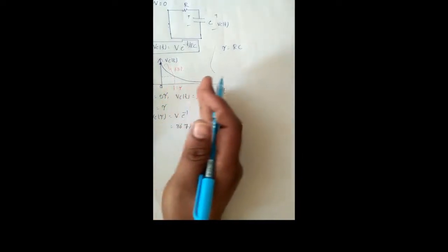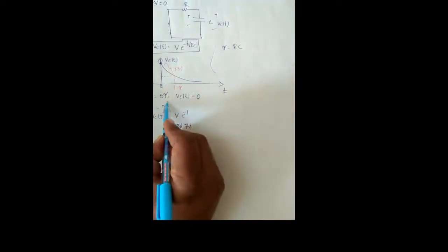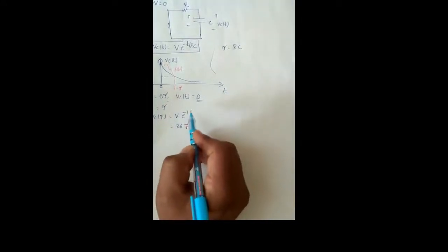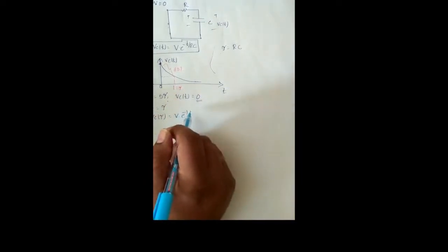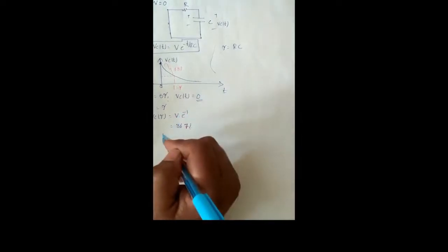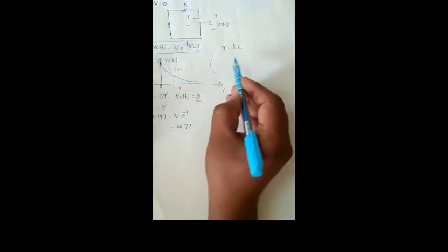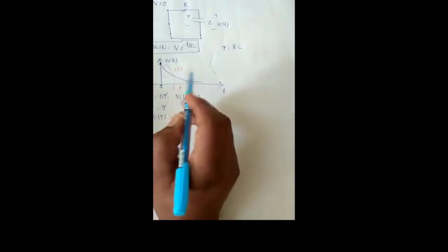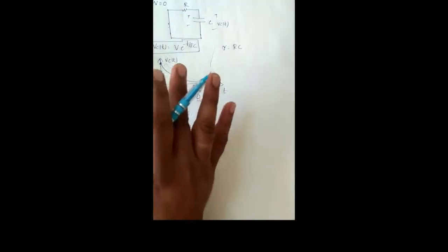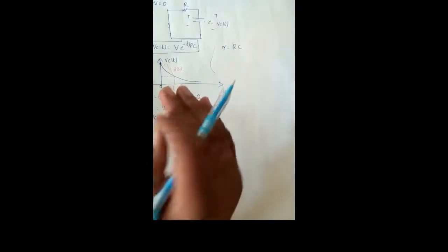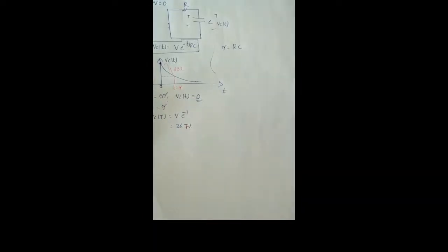And if you keep on increasing the time, at t equal to 5 tau seconds, the capacitor totally discharges to 0 volts. Okay, now with respect to this explanation, we conclude that the capacitor charging and discharging depends upon the time constant tau equal to RC. And here the capacitor discharging and charging action is helpful for understanding the operation of the clamper circuit.